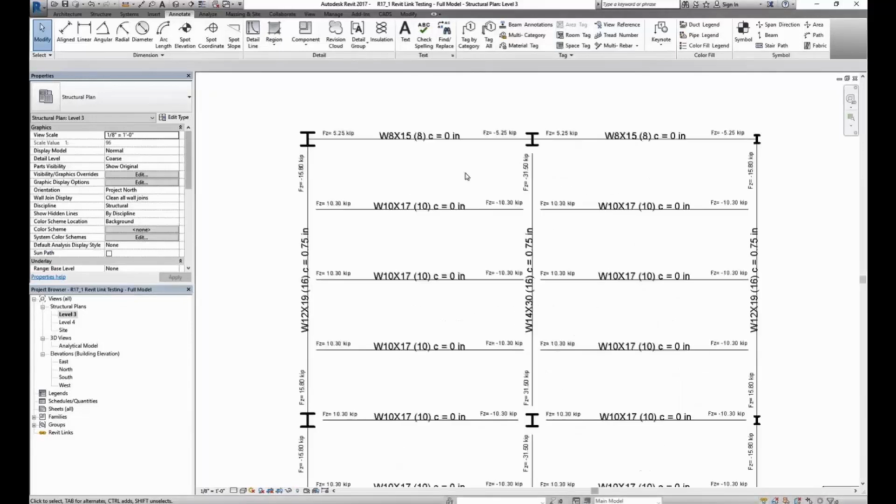So we can see exactly what we needed: we have the framing tags that include the studs and the camber that was designed in SCIA. We have the reactions, in this case just shear reactions because they're just pin connections. For the end reactions, if we needed moments, we could enable the MZ moment to show the moments on screen. And so all this information is available so that you can provide it to the fabricator or the architect or whoever needs this information for design purposes. And so that data is all available.